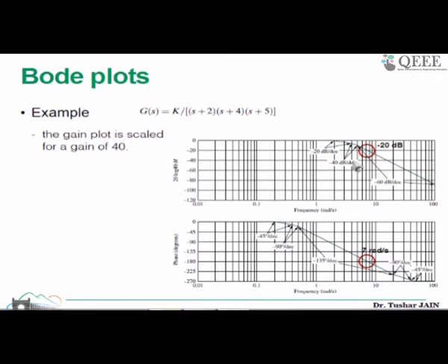Since I'm in this region, basically you won't be going into the positive region, because your graph itself starts from there. So here you see that when you choose the value 40 for this gain K, your system is stable. Now you also need to know what my range of K would be, so that I can say my system will be stable within this range of K.